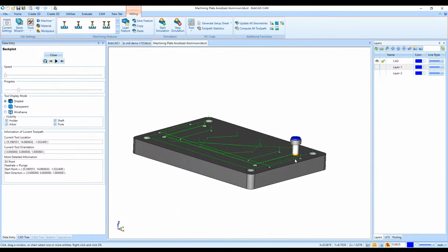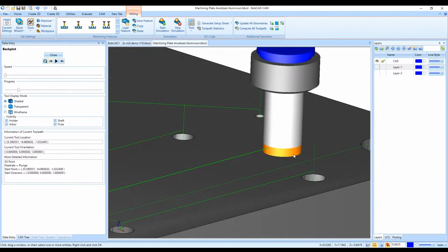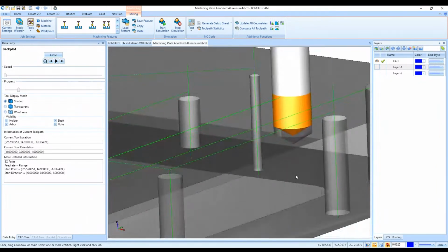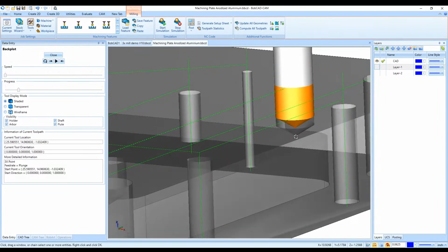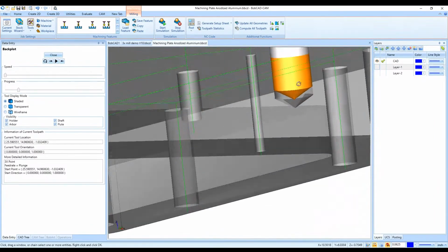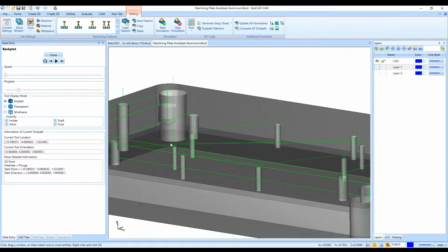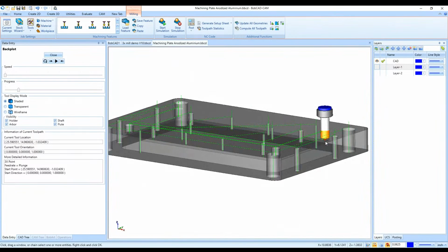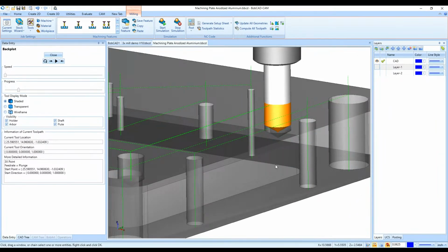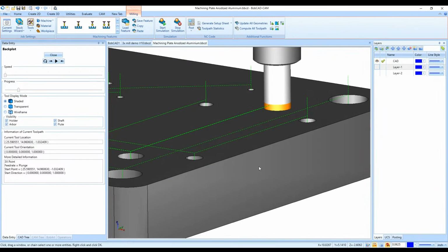And then if I get to a certain step like this one here, I want to make sure it's getting to the right depth here. I'm not sure if it's at the exact location I want. I think the tip of the tool is getting to the depth, but not all the way down. So I can adjust that as needed. But right now I'm looking at the sleeves of the holes, the surface is there, by making the solid transparent and then making it back into a solid.